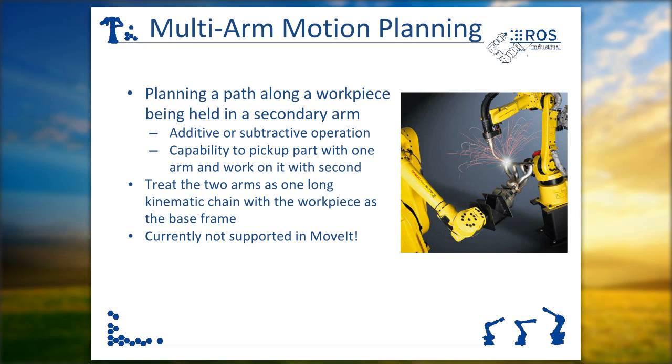It's pretty difficult. I think the approach that I would take initially on working on this would be to treat the workpiece you're working on as the base frame, as your world frame. So considering it like not moving, and then you can really just consider both the arms as one large end effector that happen to be attached by the earth, by the surface.